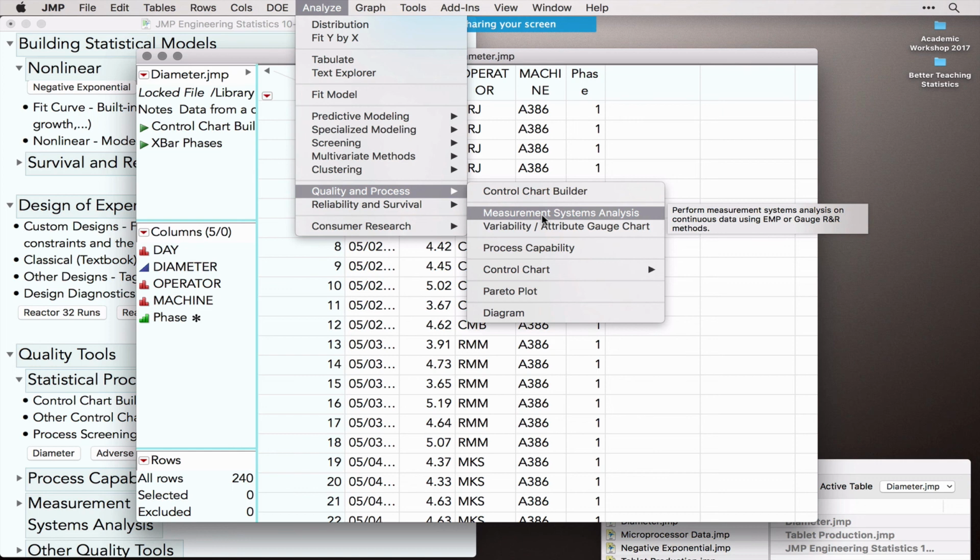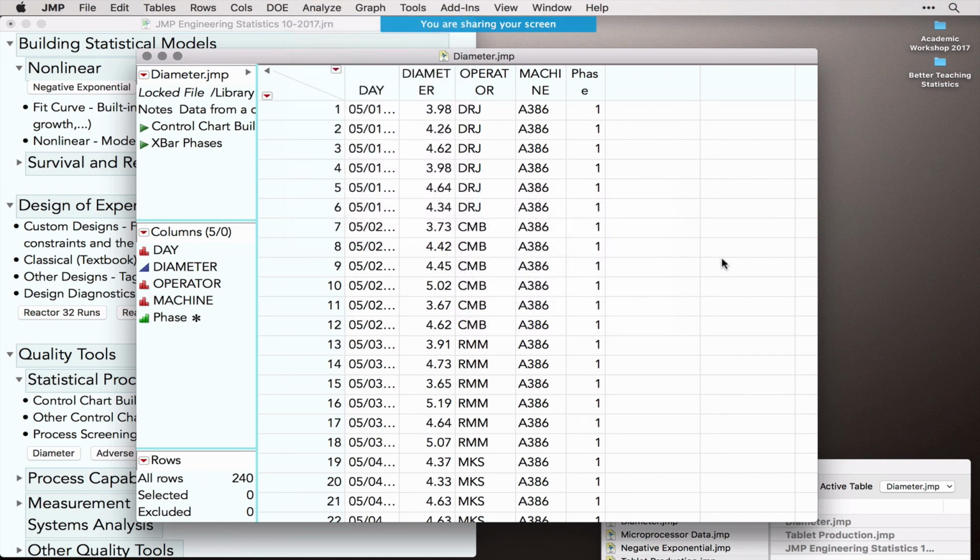And at the beginning, you should always check your measurement process and measurement systems, and for that we also have different ways in JMP to explore this further, including EMP, the Wheeler's method, evaluating the measurement process. But this really tells you where the variation is coming from. You see, you typically want to separate parts, but you don't want to see a lot of noise created by the measurement system or by operators or the measurement process. So that can be tested in the first place before you move on to testing stability and capability.